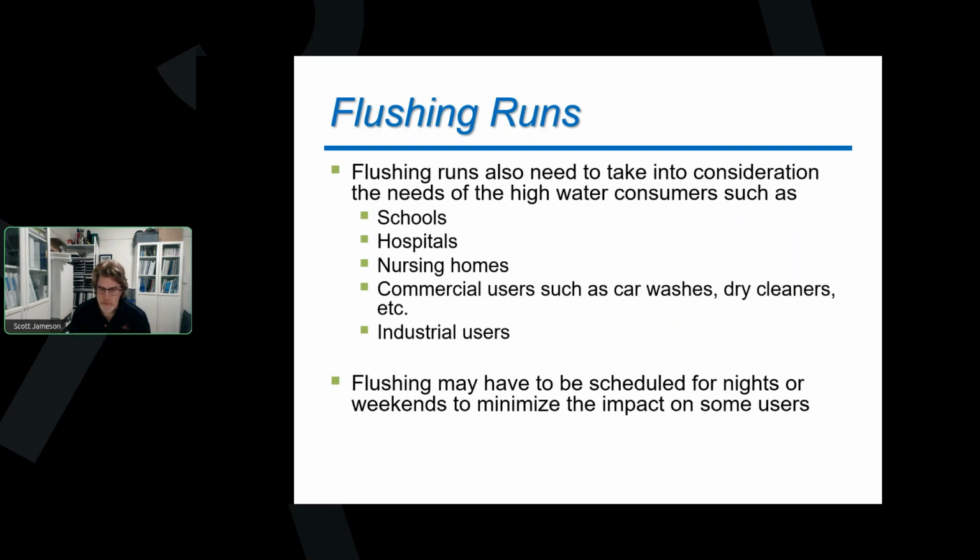And for those ones, once again, we've got to think up a plan, right? How are we going to flush by this location without disturbing this location? And for some of those, it might be that you're just going to have to do the flushing on a weekend while the school is closed, or you might have to go in at night. Right, we're going to have to do flushing at 7 o'clock at night because we're going to go by the commercial area or the place where the cafe is. So we're going to go by when they're closed and not disturb them while they're open.